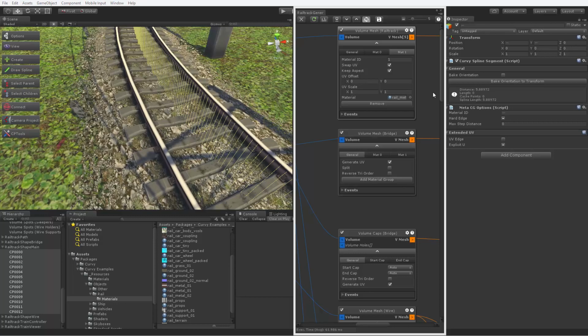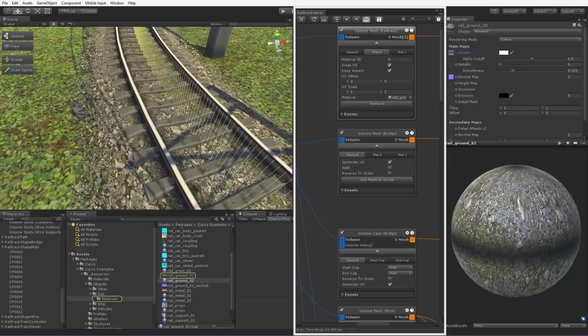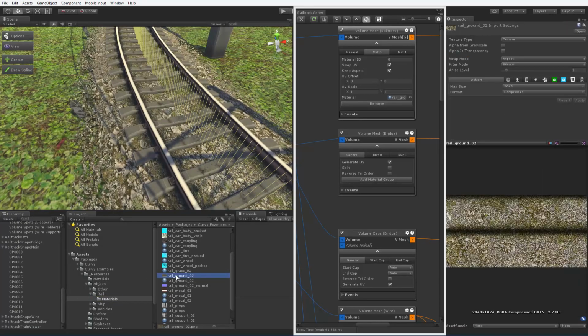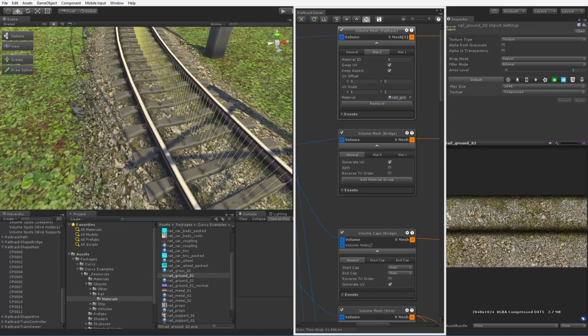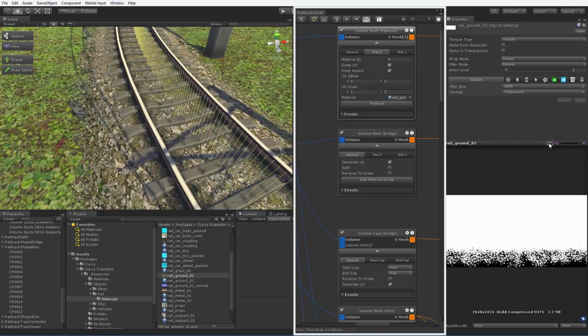Let's take a look at the material. We have a simple square texture with two tiled strips, solid ground on top and a transparent edge on the bottom. How can the volume mesh module know the texture coordinates we want on all those vertices? We want the bottom strip here and here, and the top strip here. Again, the module can't know it, so that information is simply embedded in the control points. You can, of course, auto-generate UVs without the need to define anything in the control points, but sometimes precise control over UVs is a necessity.